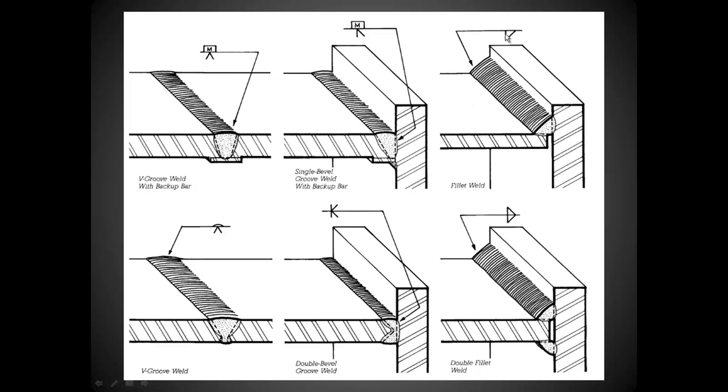And then of course we have our fillet weld, and this is just two pieces of metal that are butted up against each other, and we run the bead of weld across. So when we see this symbol, it's interesting to note that the side that the symbol shows up on is opposite the side that this is in. So when it's on the opposite side of the line, it's on the near side. If the fillet was on the top only, we'd be welding on the bottom side of this.